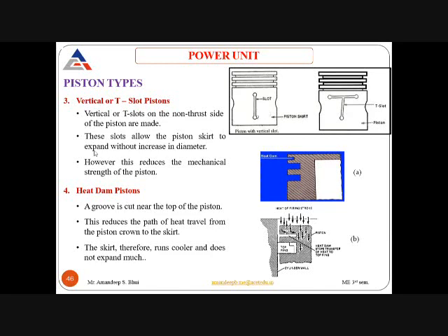Now these slots allow the expansion, so the outward expansion of the skirt is not allowed. Because of the heat, the piston skirt can expand internally towards this slot. That is why these slots allow the piston skirt to expand without increasing the diameter.